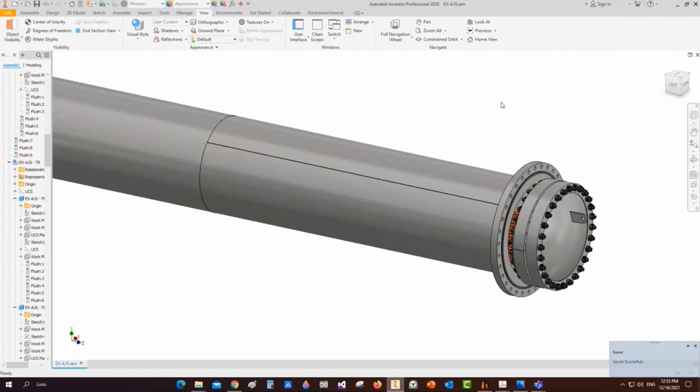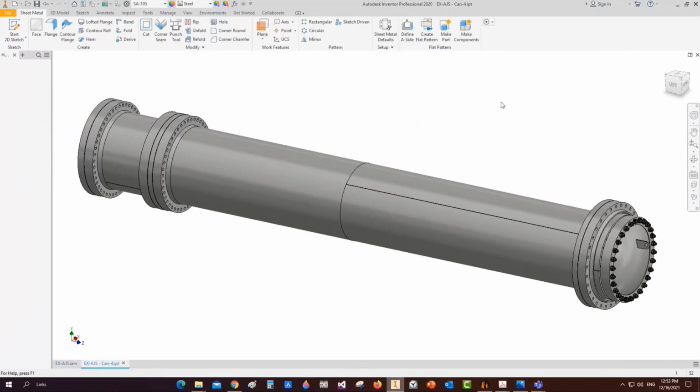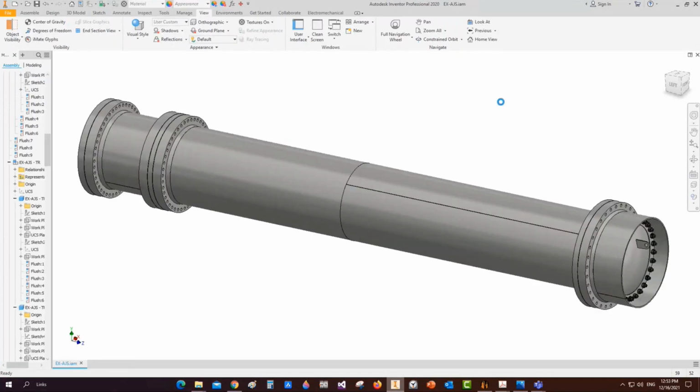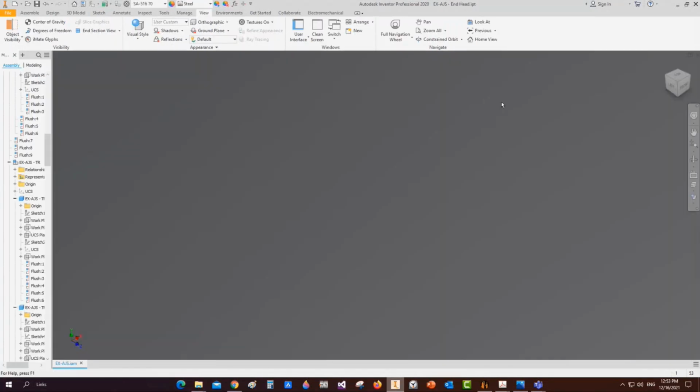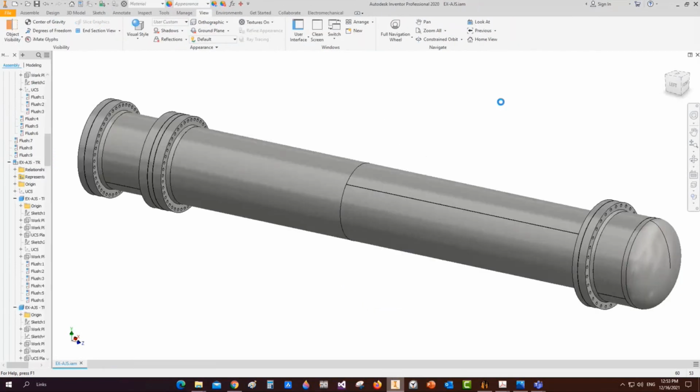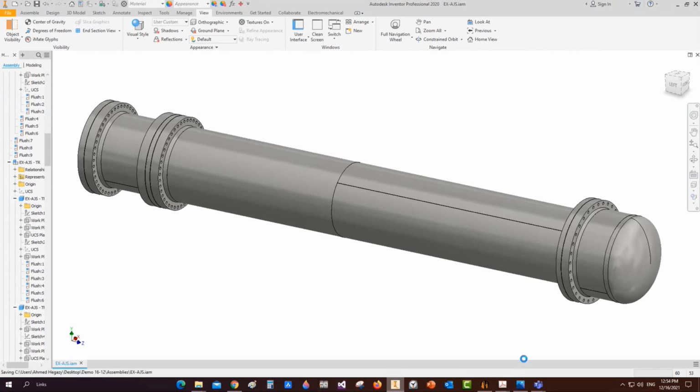As we discussed, if you would like to make a separate drawing, you can make a group for some elements to prepare them to generate a separate drawing for them. Now, after finishing the bonnet, we will start creating the support saddles. After saddles, inshallah, we will add the nozzles, the service nozzles and lifting lugs for this heat exchanger.